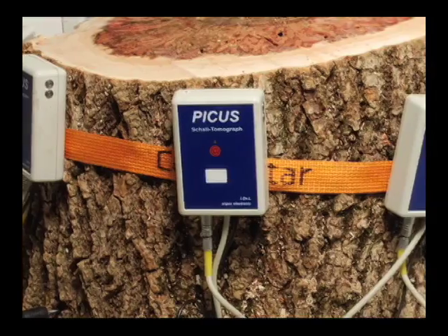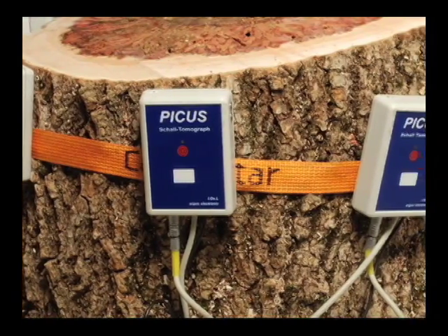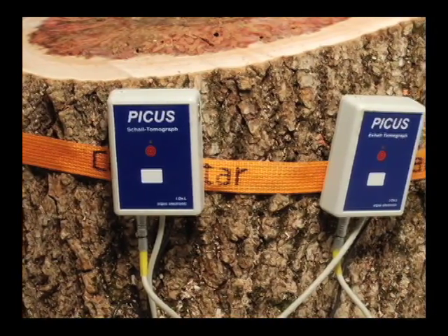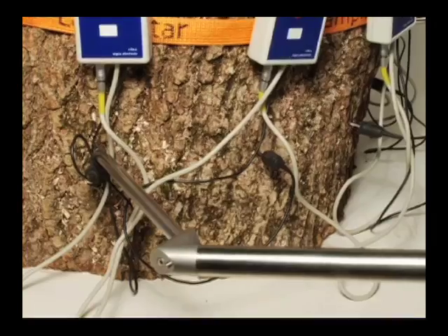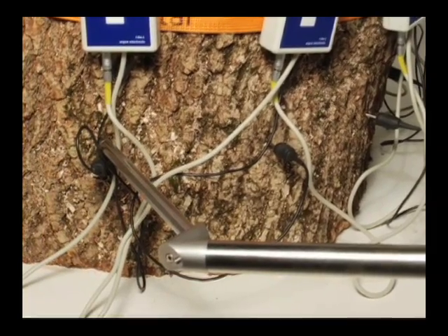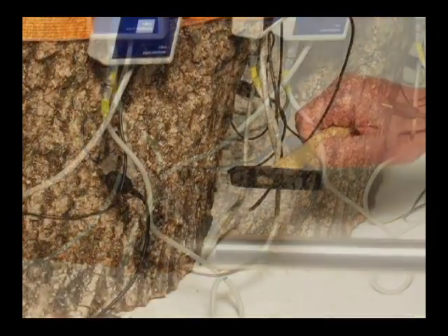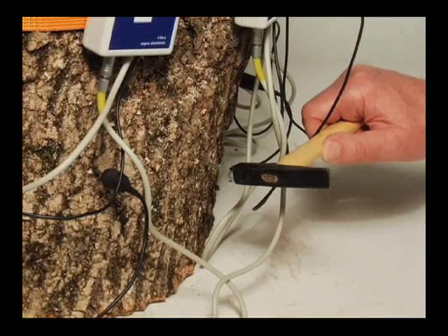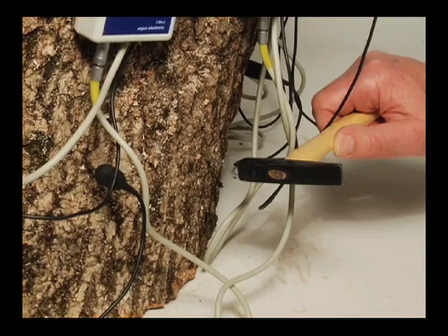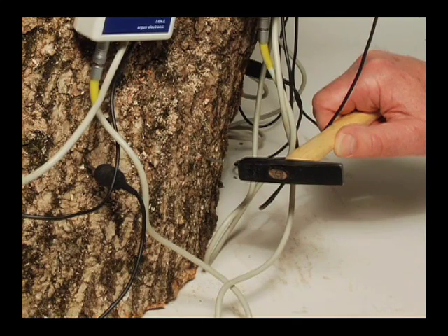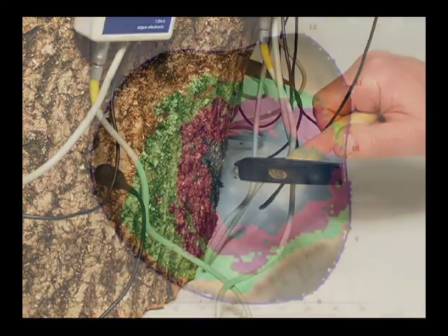Acoustic tomography employs multiple sensors, usually 8 to 32, to measure stress wave transmission times at multiple directions. The distance between the sensors is measured with a caliper scale. An impact-induced stress wave is generated by striking each of the sensor recording points with the hammer. A computer records the stress wave's time of flight to each of the other recording points. Knowing the distance and the time of flight, velocity can be calculated by the computer.